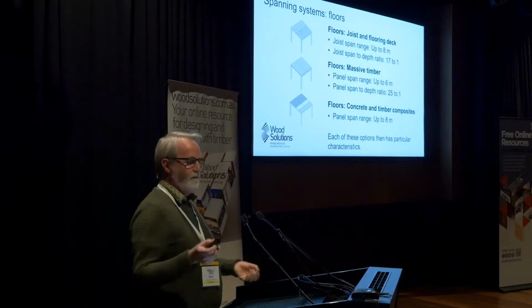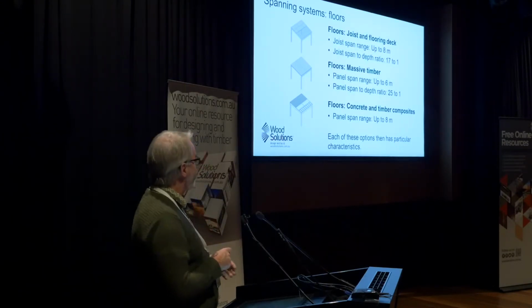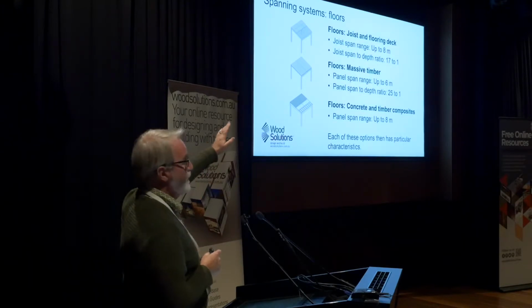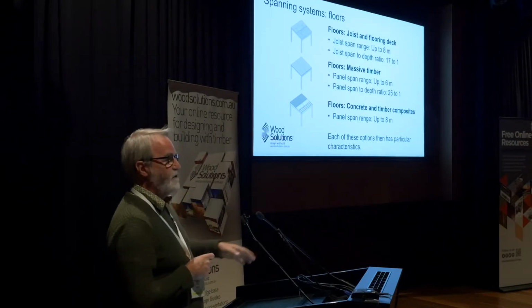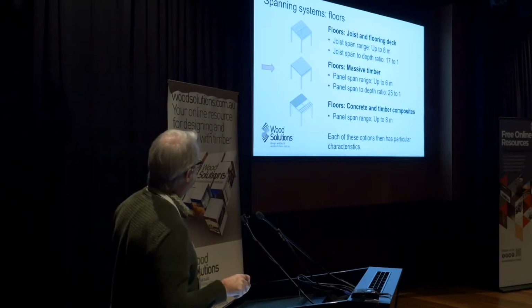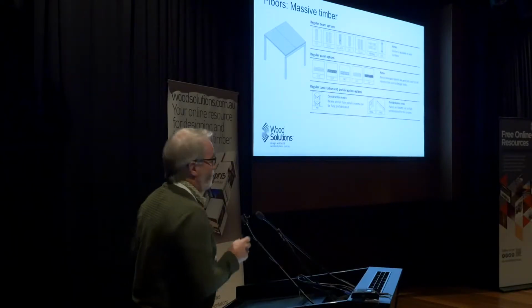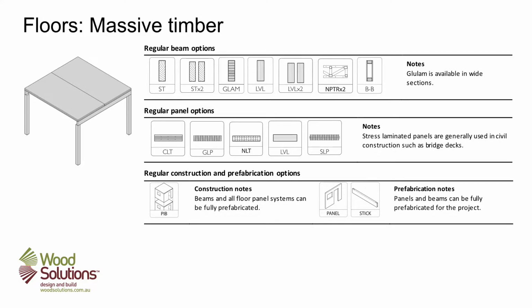We could probably go further, but we're not trying to do gymnastics with this too much. And then we're giving common span to depth ratios for systems that you may use in these cases. Now, if we take massive timber as our example in our project, we would then go to the detail in the guide of massive timber option.